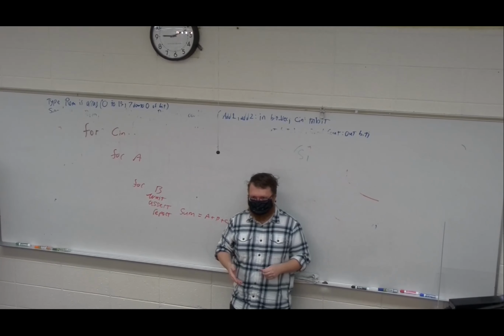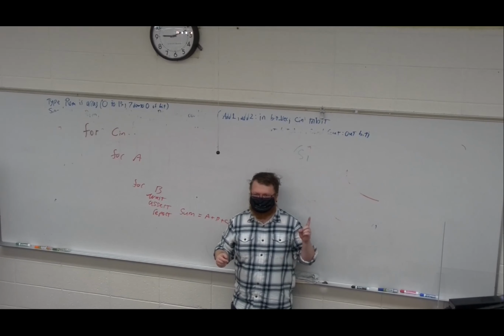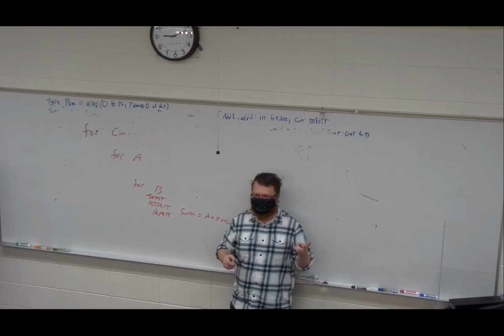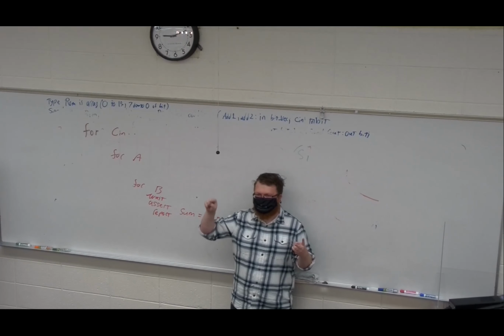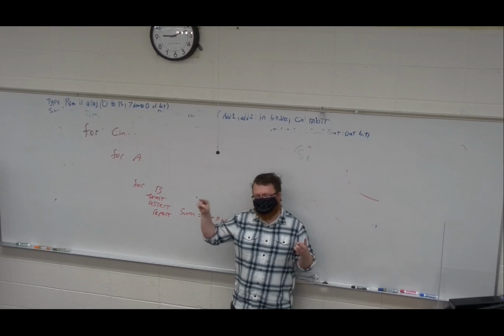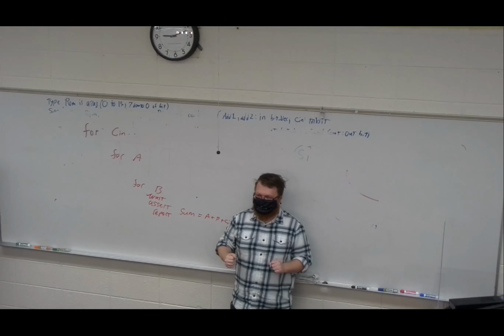That's not a good way to do it. Instead, in Vivado, we can access internal signals of these modules by clicking on the side tab listed as scope. Then there's a side tab called objects, and you can browse through the hierarchy, find these internal signals, and drag them into your waveform to see what's going on inside.